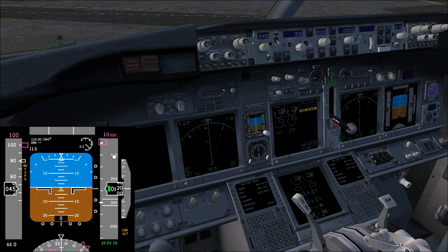We have again an indication of the autopilot commanded altitude. Now it is 10,000 feet, a window that is out of scale, so it is positioned here, and actually this is commanded by the altitude knob only, and maintained by the FMS and the autopilot VNAV configuration.